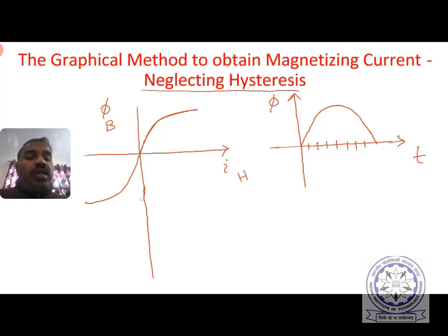Now here I will take the time axis t. It is independent from this BH characteristic. I am cutting the BH characteristic here itself. Now I am plotting my y-axis here, which is current, because I need an axis parallel to the I-axis of the hysteresis, and here this flux axis is parallel to the flux axis of the phi-t characteristic.